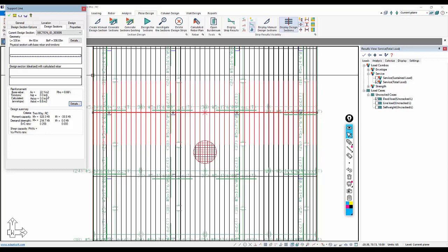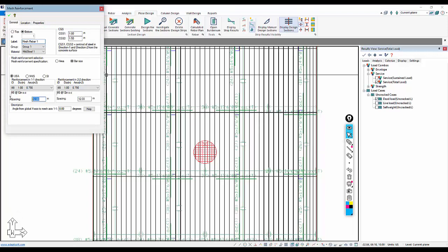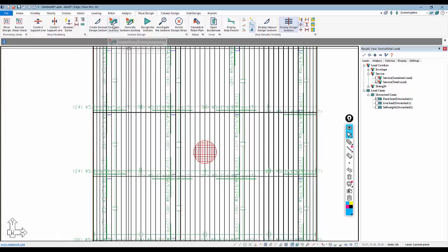I only needed 6 per the calculation we looked at earlier, so I'm going to drop this way down so it's just under 6 square inches. And I'll actually space this at, let's do 40, actually 50. We said 48 earlier when we calculated that for the spacing. We'll do 50. And again, we're going to design the cuts.